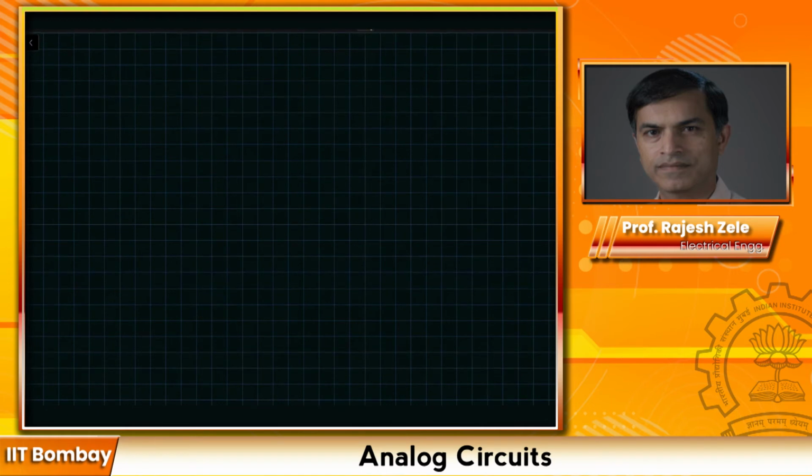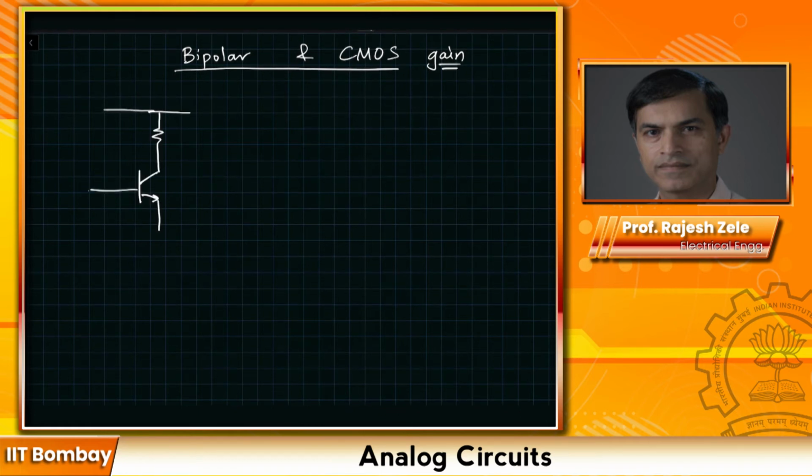So what we are going to do is we are going to compare bipolar and CMOS gain. That's what we're going to do. And we're going to keep the same topology. So for example, on the left side, I'll do the bipolar topology. And for the purpose of this discussion, we will just have a DC voltage source here of bias. And this is our V in. And this would be V out, RL. Bipolar transistors are denoted with Q. Say this is our VDD.